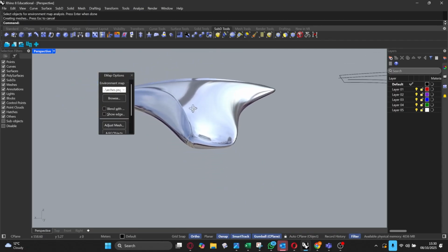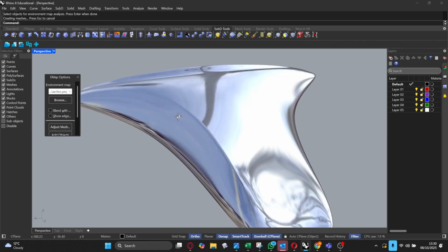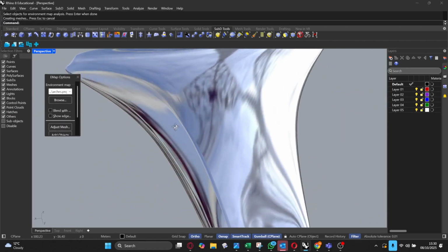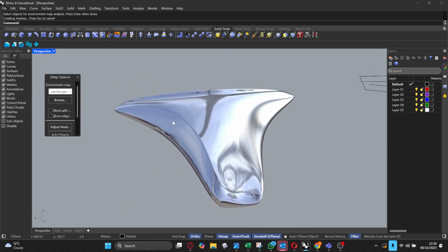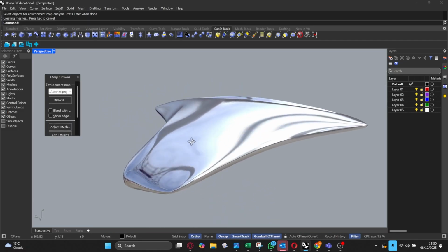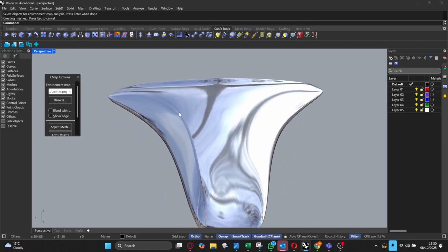And you'll see that crease that's now appeared. Just by putting that crease on that edge, it will blend the crease. I did it at 100% there. So it added that creased edge just to this part, and then it starts to soften back to this edge over here.